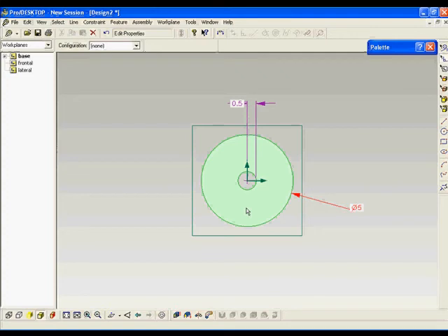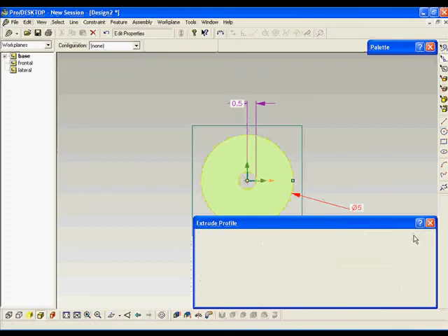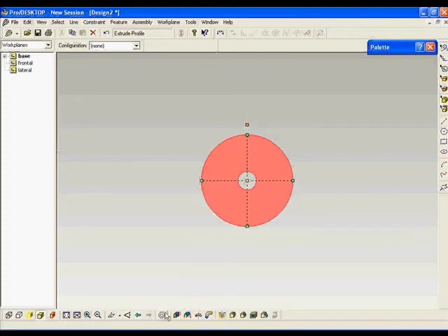So now we're going to extrude this from a 2-dimensional orthographic view of concentric circles into a 3-dimensional pictorial view, which will become the wheel. The thickness of the wheel should be 2.5 inches. You'll notice that it started to turn yellow, showing that it's converted to a 3-dimensional view.